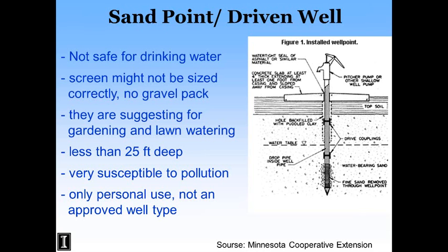If your aquifer, your shallow aquifer, is say 50 feet thick, you're much better off putting in a drilled well with a screen near the bottom. It's more protected. Sand's a natural filter. The more sand that water has to travel through to get to your well, the more it's likely to filter out, especially bacteria and organisms and things that might come from the surface.